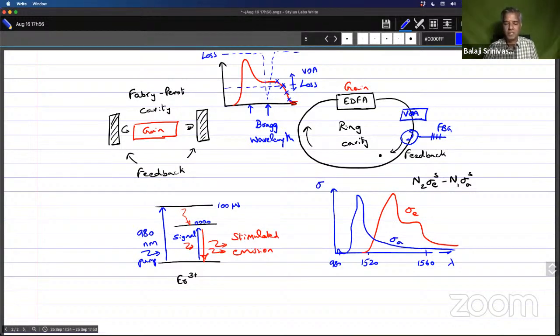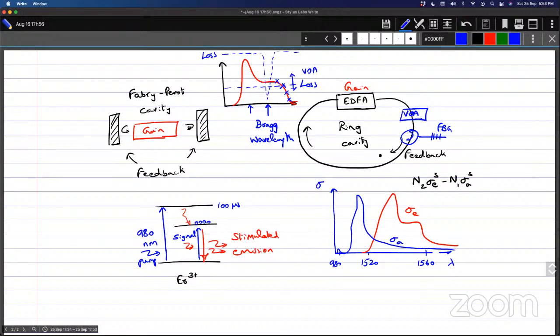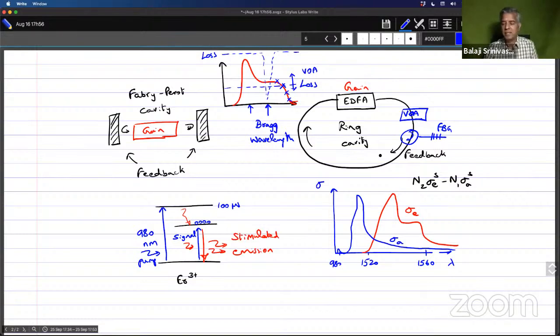But if you want to get performance out of the laser where the emission wavelength is rock solid, only at that one particular wavelength all the time, then yes, you have to use an FBG or some other device where you can get this sort of loss spectrum. So those are the applications where you have to go for that element.